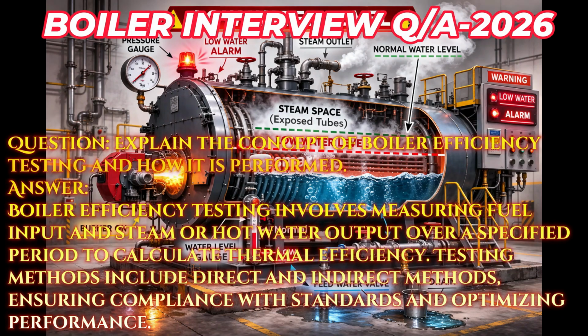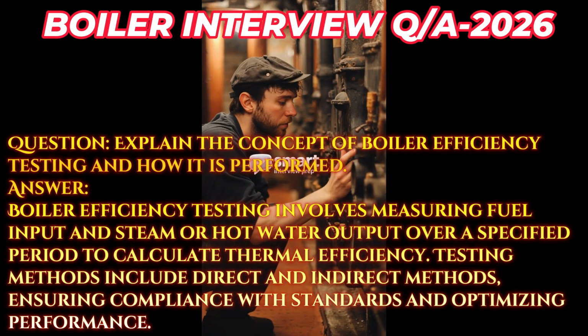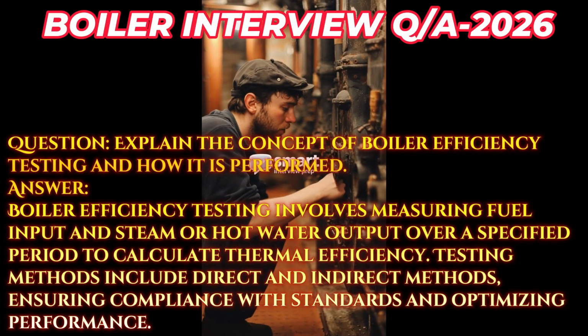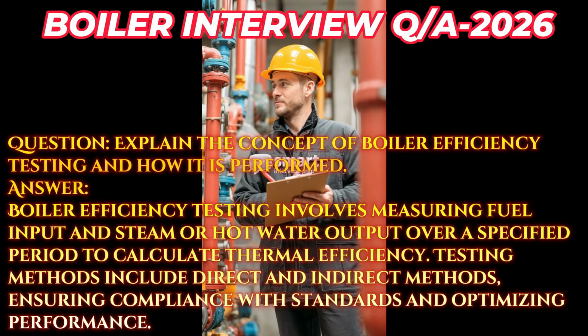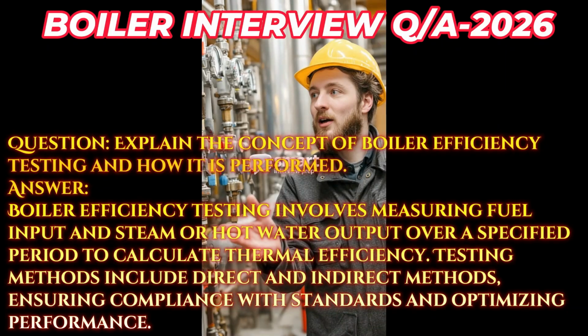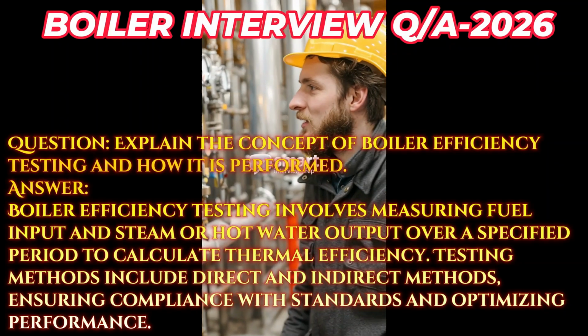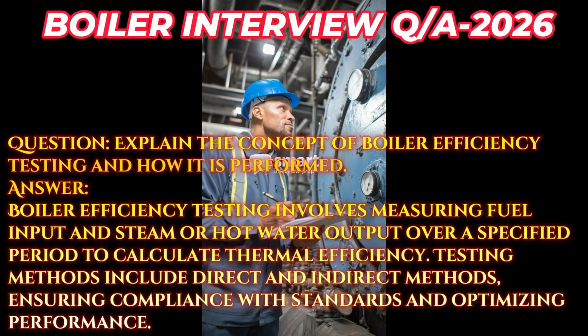Question. Explain the concept of boiler efficiency testing and how it is performed. Answer. Boiler efficiency testing involves measuring fuel input and steam or hot water output over a specified period to calculate thermal efficiency. Testing methods include direct and indirect methods, ensuring compliance with standards and optimizing performance.